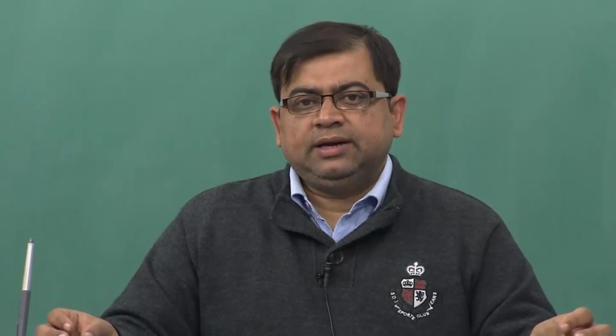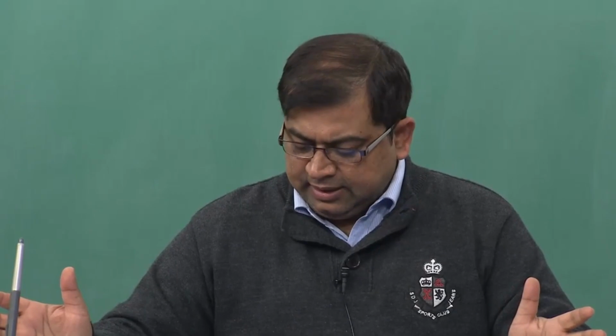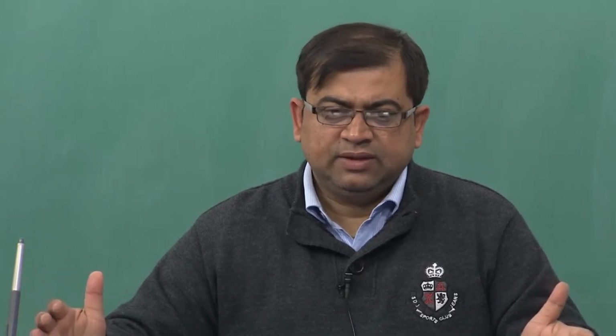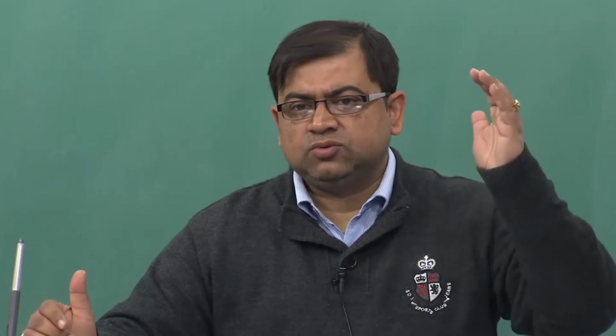So, with this I would like to end this module, but in the next module we will try to look at some of the nitty-gritties of this iron carbon equilibrium diagram in terms of structure, etc., and there are in fact many points which formulate, namely the eutectic, the eutectoid and the peritectic points. So, I will tell about those transition points and what they physically signify. It is only a way of representation of the percentage composition as a function of temperature and how they coexist in one phase or how they coexist in the other phase, or maybe if there is a solid liquid combination. So, that is a one snapshot explanation that comes out of this one page equilibrium diagram of any constituent.